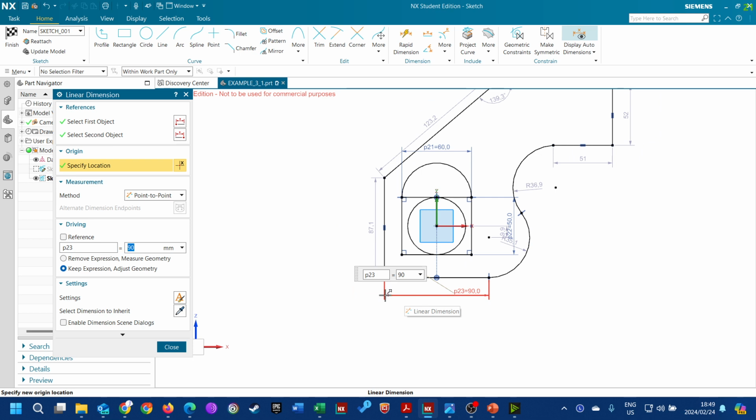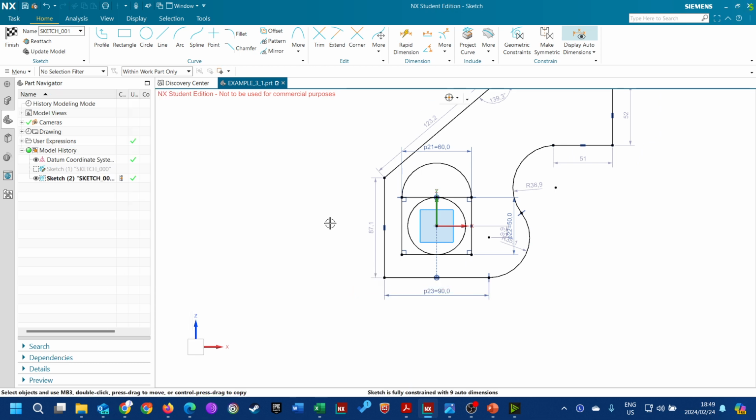Something I now do also realize is the line is not actually in the center. I misread the sketch. I saw now that there's actually a distance specified from the edge to the midpoint. So to remove a constraint, you can just click on that constraint and click on the X, deleting it. So it's out of the way. So we want to add a distance between this side and this vector.